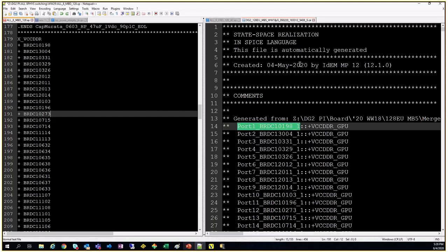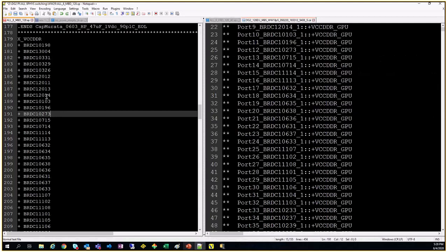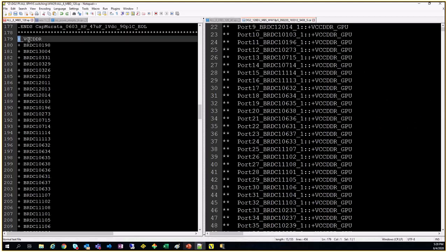When you're instantiating your circuit file ports into your main SPICE deck, you type X underscore something, preferably your rail name, whatever rail you're doing. Then you write plus. This plus sign is important. Basically this should all be written in one line, like one large line.